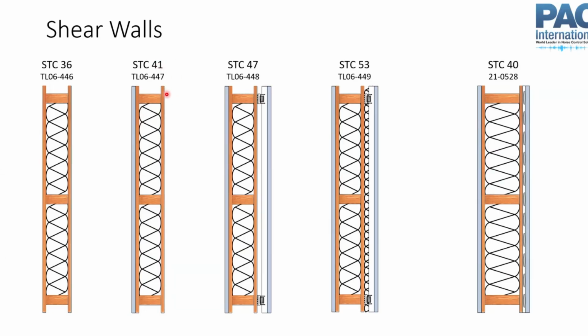So what we want to do is break that structural path. One of the ways that we could try to do that is with a resilient channel, but that creates this very small air cavity here. And so while we have essentially decoupled that structural path, right, the shear panel can move somewhat independently of the drywall. That's very small airspace. The air in there moves as a spring. That air has some stiffness, right? And that's how sound is transmitted. I mean, that we hear. It's through air. And so if the shear panel moves, that air in between moves, and it moves the drywall still. So we need to really expand that gap between the two.